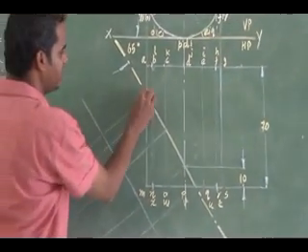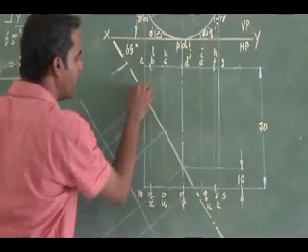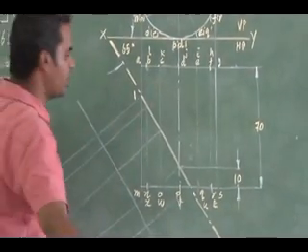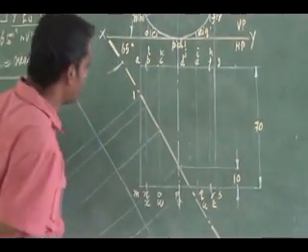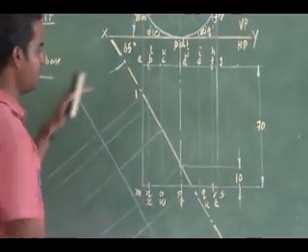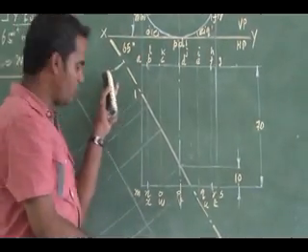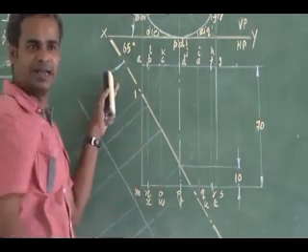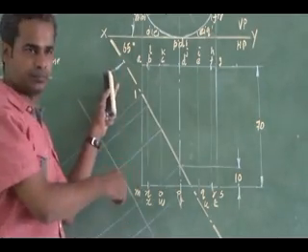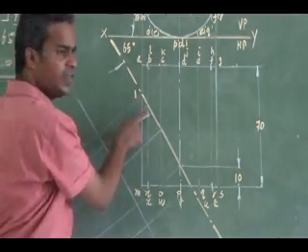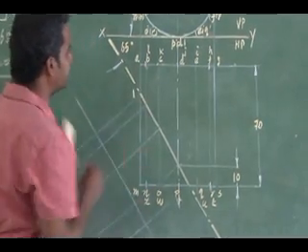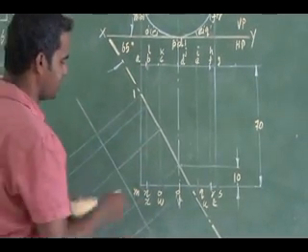Now, we will give the cutting points in order. From the left extreme, I am marking the cutting point 1. That is my visible cutting point, which cuts the generator MA. Listen all of you, MA. Then you go along the cutting plane, it cuts the visible generators.